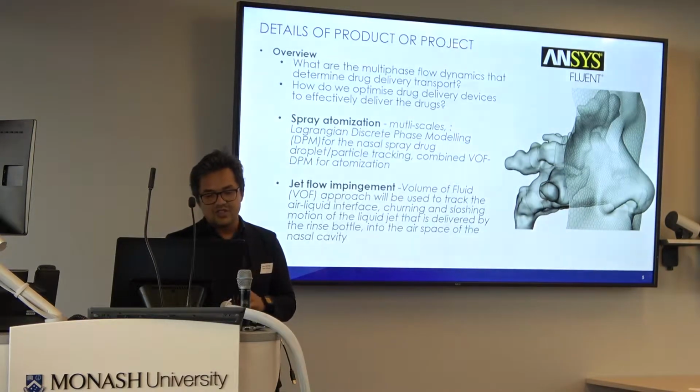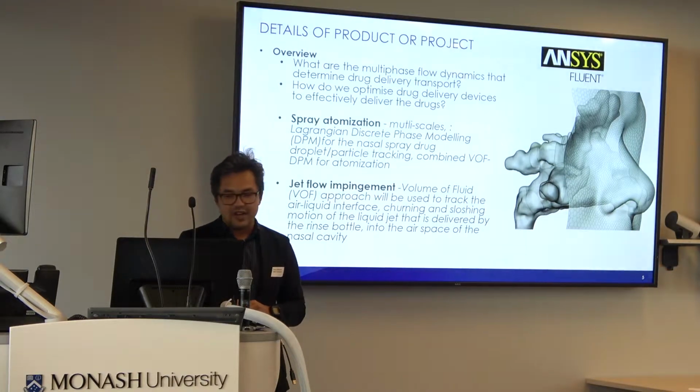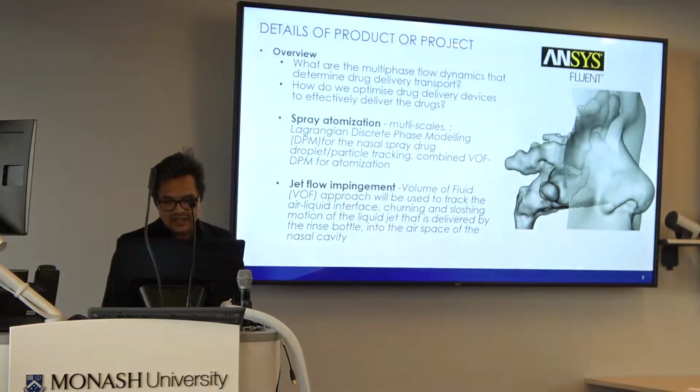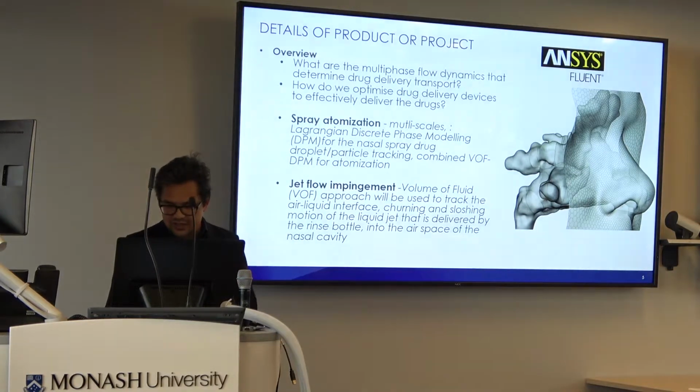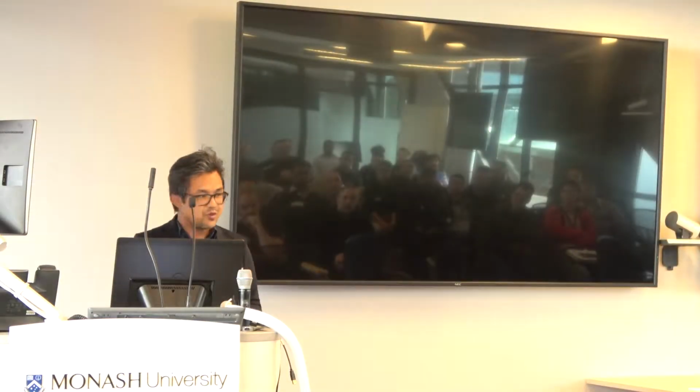And then we've got just the single volume of fluid approach, which we can track the interface of the liquid, the jet stream coming through. And this is the polyhex core meshing.